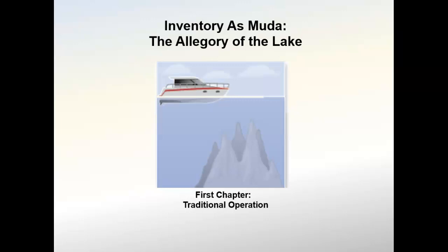Now, safety stock is one kind of inventory common to a traditional production system, yet particularly troublesome in the philosophy of lean operations. Contrary to the spirit of just-in-time, safety stock represents idle goods being held just in case. This inventory is intended as protection against some uncertainty in the future, such as an unexpected surge in demand or a possible future failure in supply.